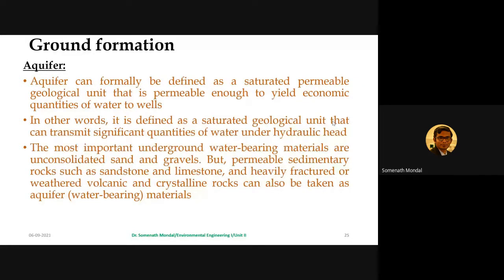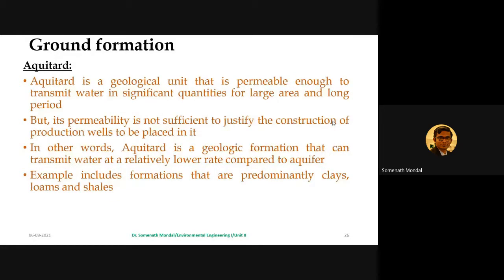We are talking about aquifer. So the thing is, I defined it as the saturated geological unit that can transmit significant quantities of water under hydraulic head. So the most important underground water-bearing materials are unconsolidated sand and gravels, but permeable sedimentary rocks such as sandstone and limestone and heavily fractured or weathered volcanic and crystalline rocks can also be taken as the aquifer and would have the capacity to bear the water. So, this is the way aquifer is defined.